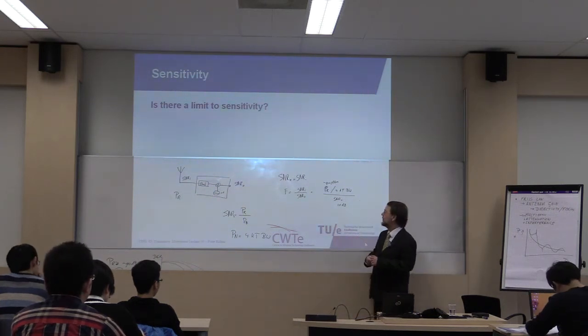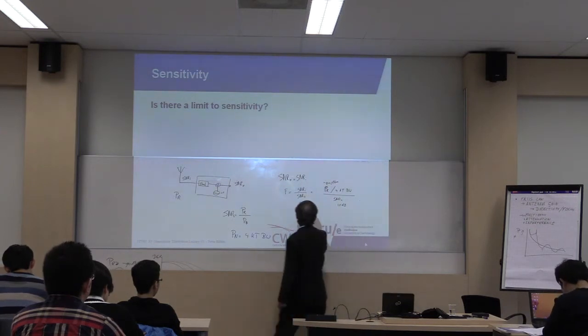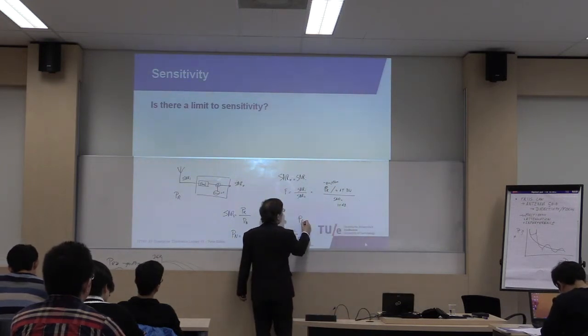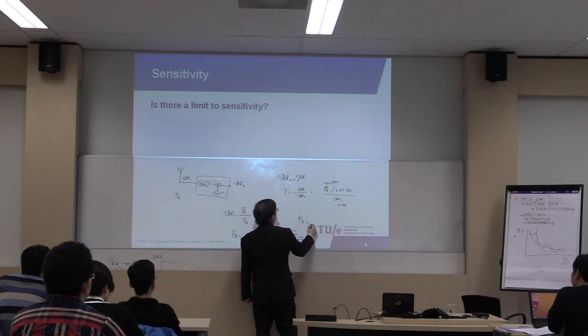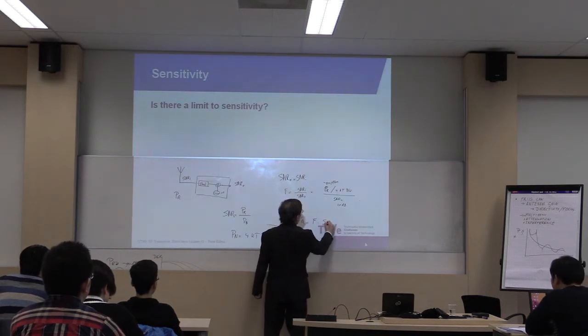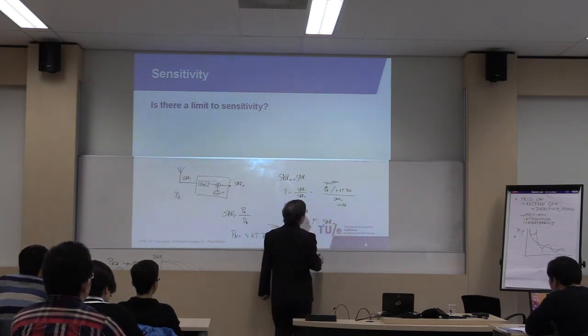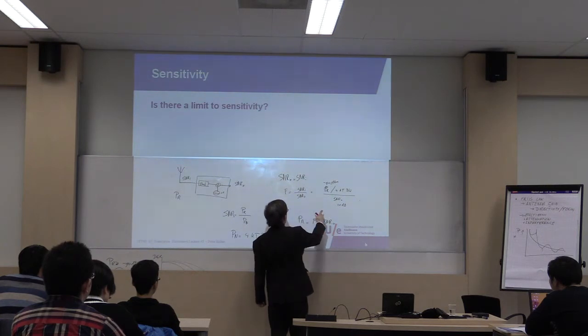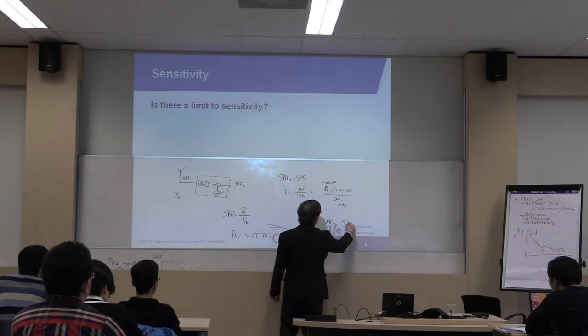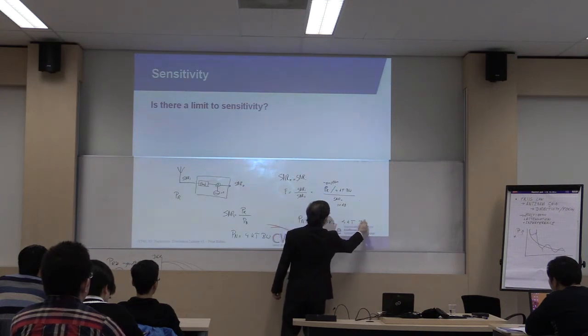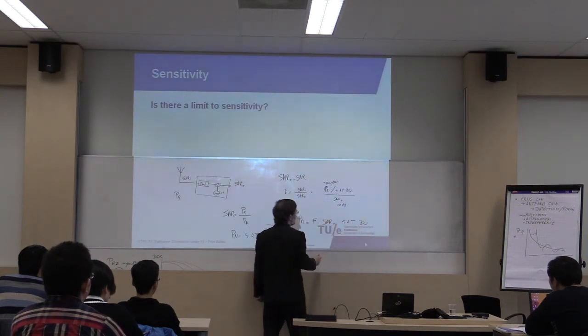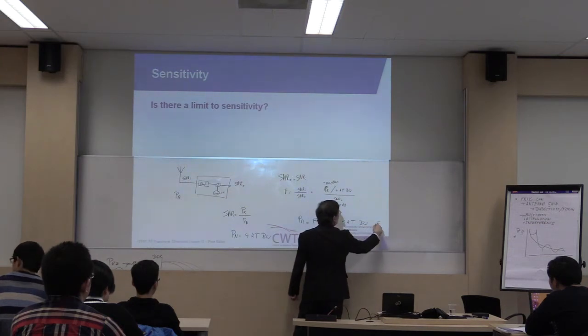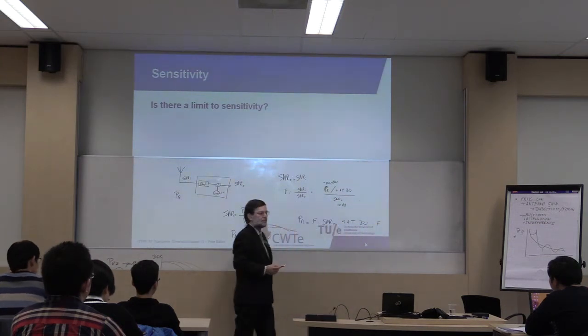Or in other words, the best sensitivity that you can get, received power, equals, and now I have to do it right, F times SNR at the output, times 4kT times the bandwidth. That's the best sensitivity, and then the noise factor makes up for the real sensitivity.